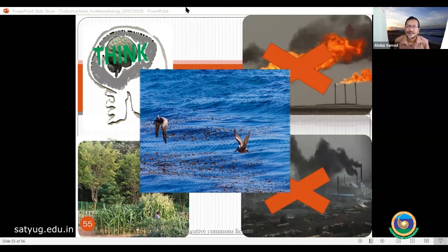Surging means that if the back pressure is very high, then it's a surge. But in our case, back pressure is not so high because it is a low head turbine, where 1 bar pressure will be normal and maybe 1.5 bar will be the maximum difference between inlet and outlet. Gas turbine is a very high head turbine.